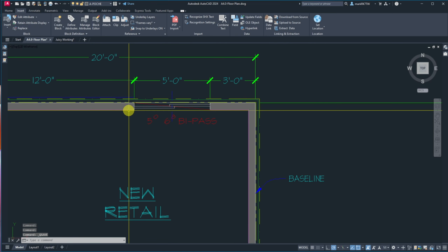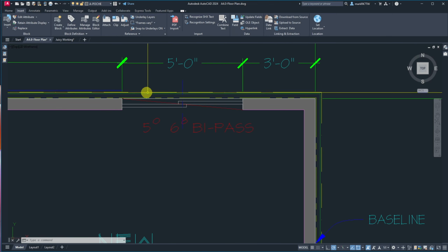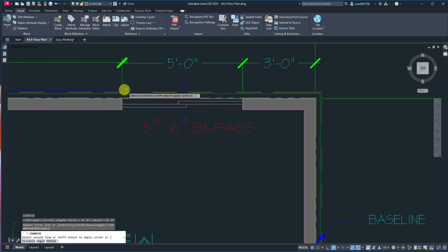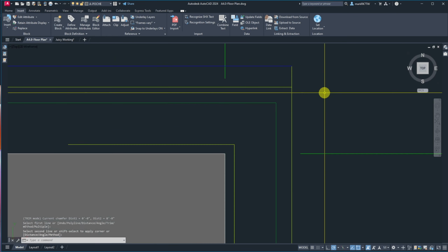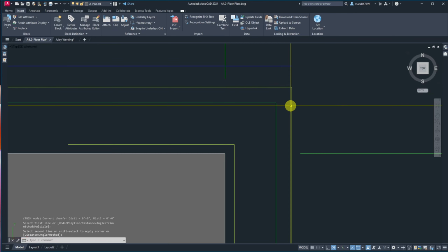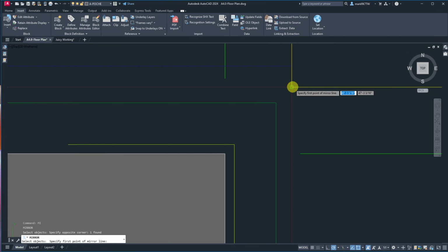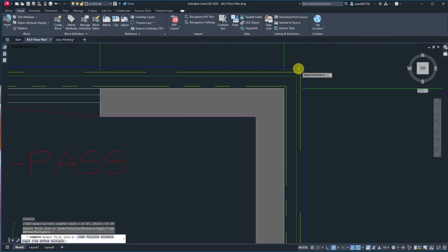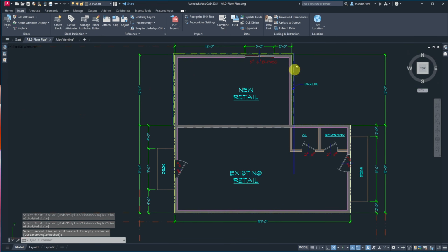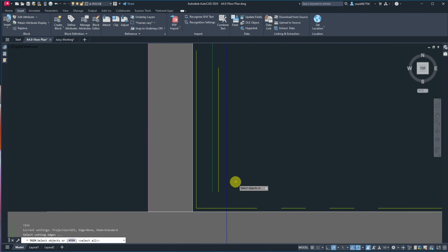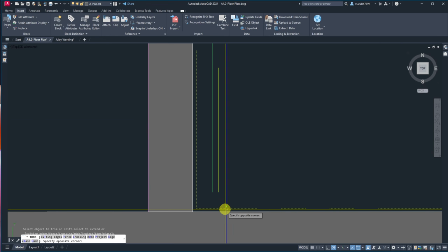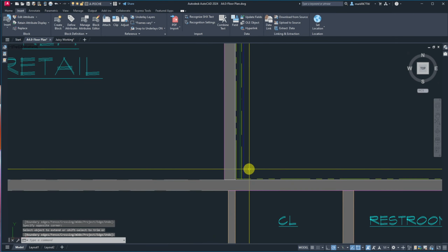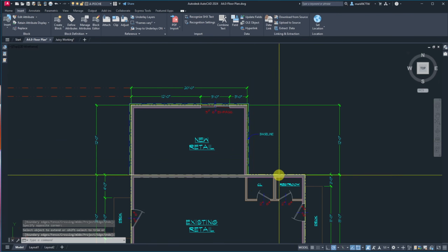But I do need to take, oh, I got my veneer is not complete. What I'm going to do is chamfer it to here, and then just rechamfer this to fix that. Then let's mirror this out at 45, chamfer it, and it's probably going to be too long at the other end. So we'll trim it back to here. For now, I'll extend those down to there. We got to figure out what's going on.